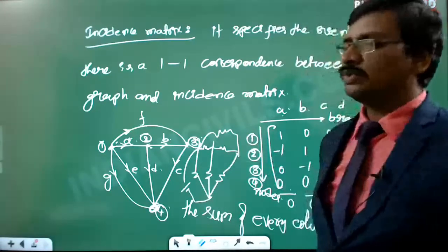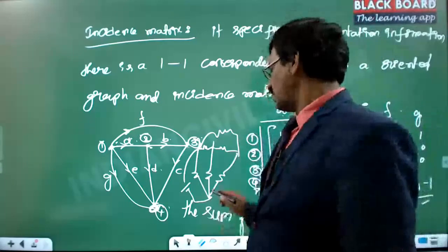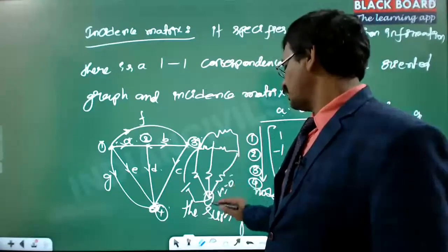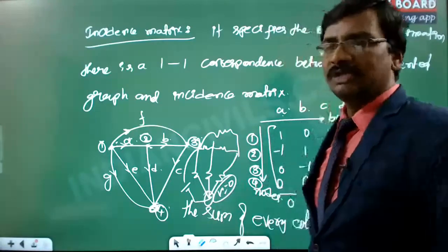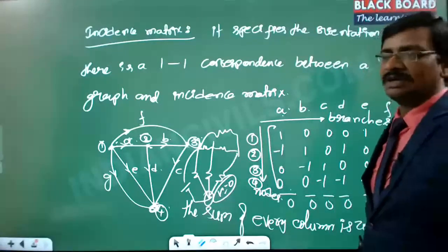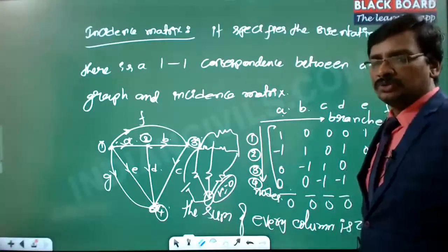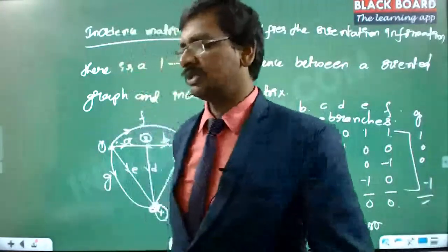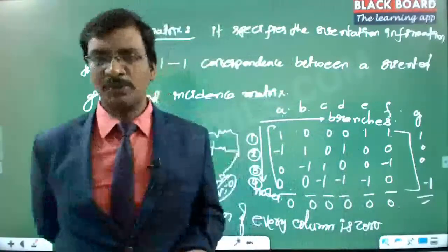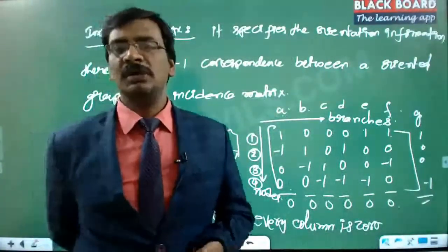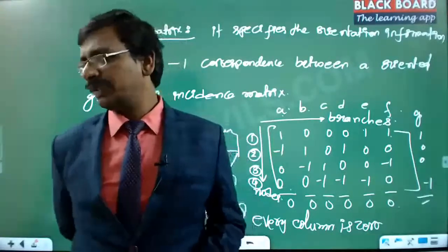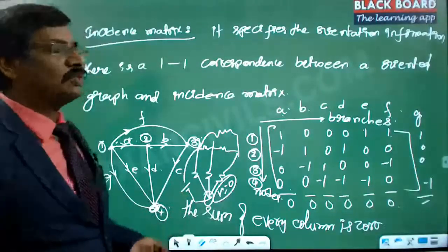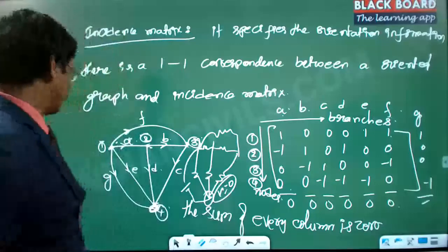If I give this, our tendency is always to take one particular node as the reference node. That means I am making this particular voltage 0. If I take that as the reference node, are we losing any information? If I consider it as V versus 0, we are not able to differentiate anything, because we get the complete information without losing anything. That's how we solve the problem: we take one node as the ground and express everything with respect to that. So taking one node out of the network, we are not losing any information. That is one important conclusion.